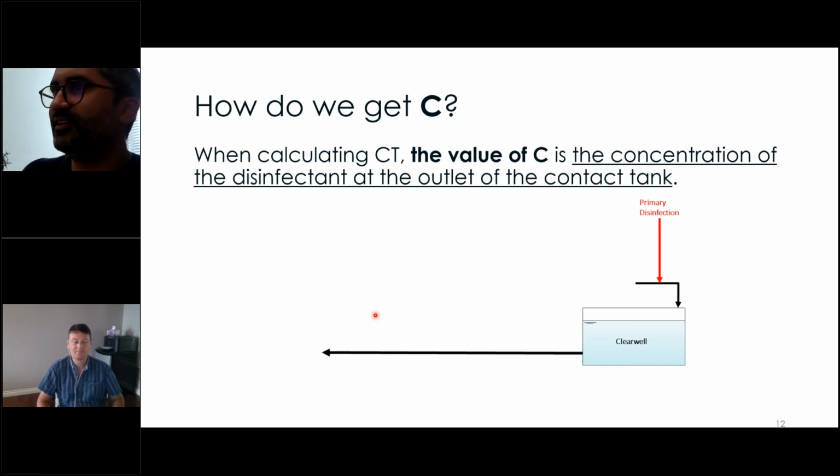Yeah, that might be a little trickier. So baffle factor is trying to indirectly estimate your T10. In that case, if you've got a unique situation, you may benefit from trying a tracer test if you can. That might require taking the tank offline, because you don't want to do that while your system is running, even if you're using a benign dye. But assuming it's old and irregular, you may not be able to get in touch with whoever manufactured it.